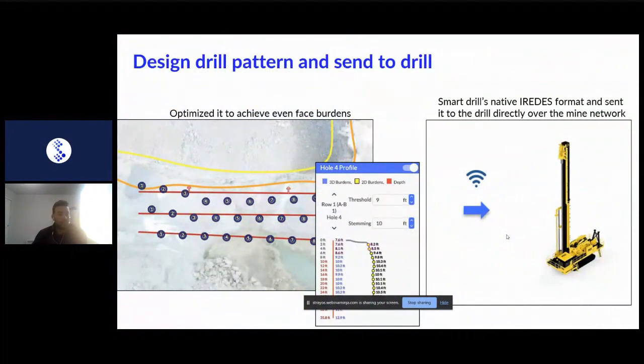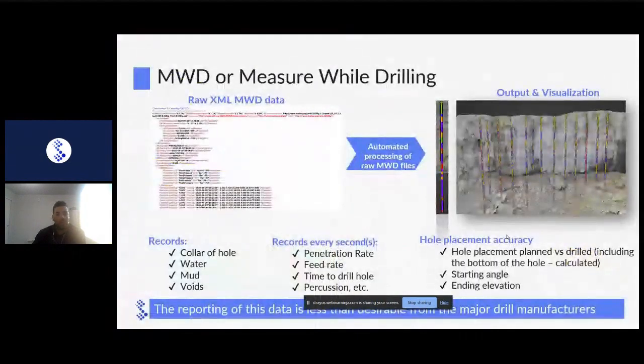So doing a digital drill design, optimizing your pattern, we'll say, having this design done beforehand, after you've analyzed your site conditions, the geology, tailoring your pattern to fit your conditions, optimizing burdens, making sure you have adequate burden on the face and in your rows to match your site conditions. This is critical. You get your information accurately done.